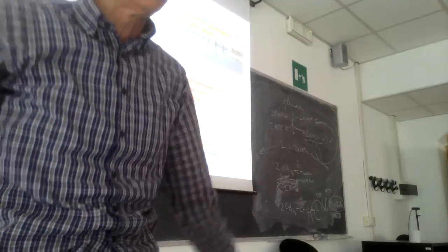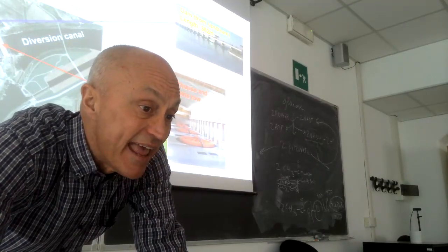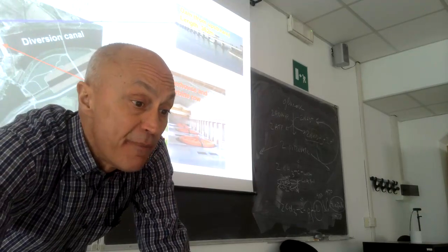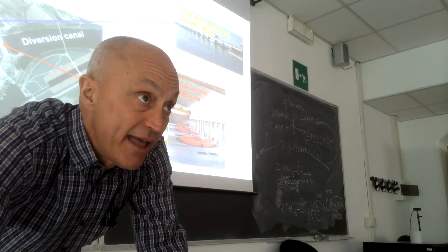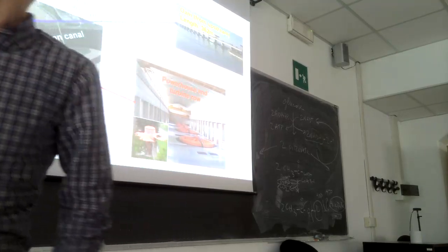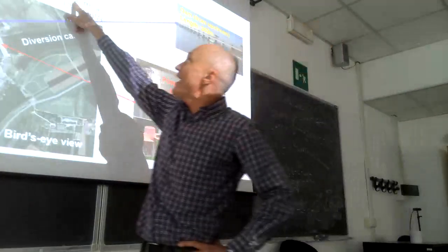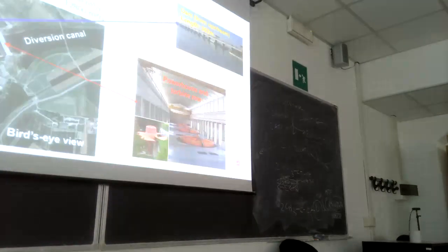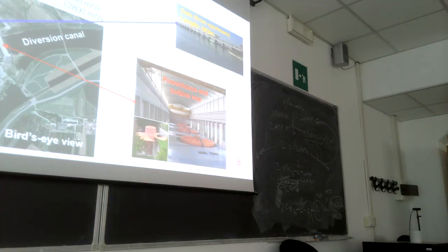So very easily, if you use that formula, 800 cubic meters per second and, if you are lucky, 10 meters of effective hydraulic head returns 80 megawatts. Okay?